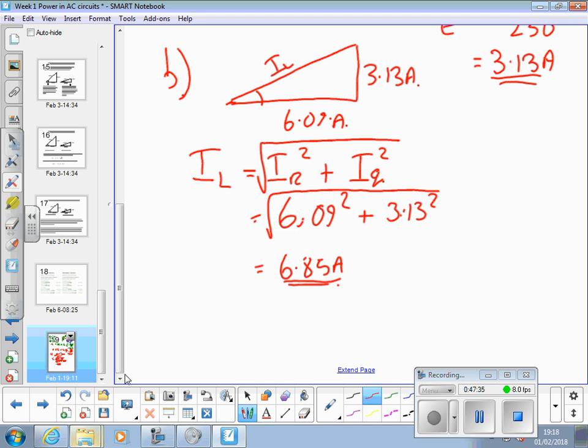Right. There are two ways that we could get the apparent power supplied by the source. Which way would you choose? S. Yeah, because they're being given. So the ultimate way here is, because you're being given P and Q, express them in the triangle and use Pythagoras theorem because they're given values. The other way would be to use this line current multiplied by the voltage.